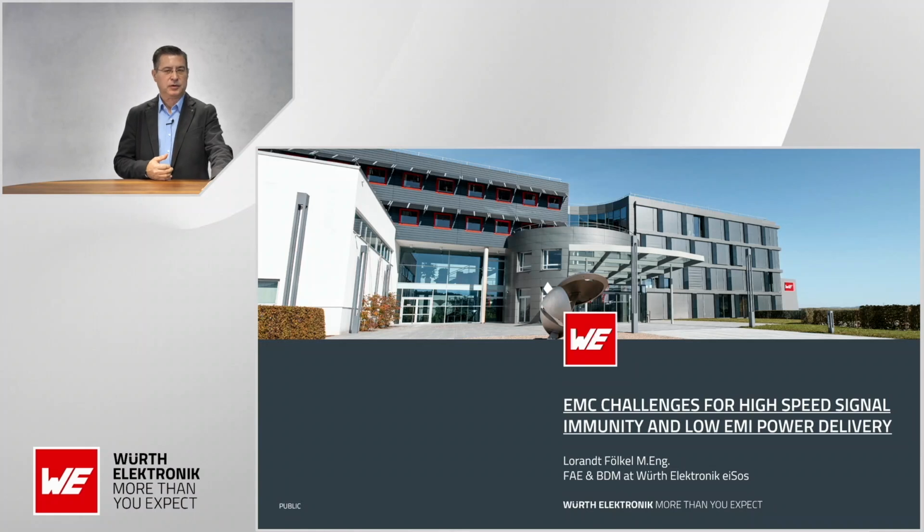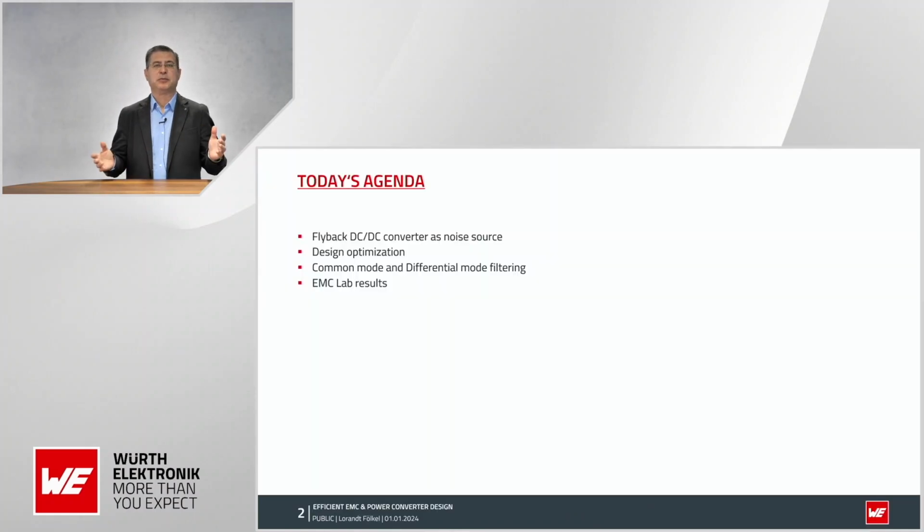So first of all, when you design a power supply, I guess the simplest way is, if you have multiple voltage inputs or a buck-boost conversion, sometimes a flyback is quite a typical, very easy design, especially when you need galvanic separation.